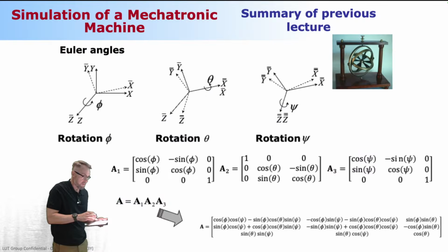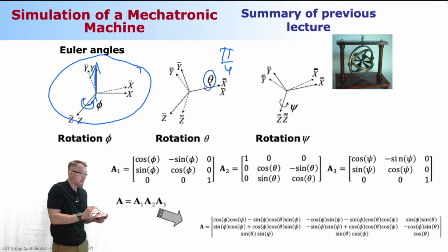Let me take you back here, which is this graphical representation. So first what you need to do is have this rotation of 90 degrees, pi divided by 2, to make your x-axis point in this direction. This is where the original y-axis is located. Then you do your rotation, which is this, I think I mentioned pi divided by 4, which is theta, pi divided by 4. And then you need to recompensate. You kind of get back to the system where it got started. You compensate that by putting this to be minus pi divided by 2. And that's your y coordinate rotation.